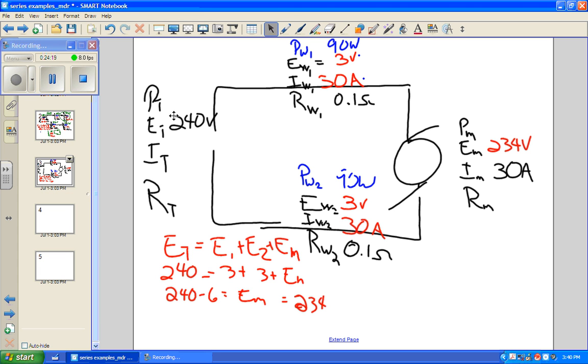So let me explain this. Even though this is a very short piece of wire, and it's not killing the motor, how many 60-watt light bulbs are we turning on that we're not getting? 3 of them, right? You're paying to run 3 light bulbs that you're not getting to do anything.